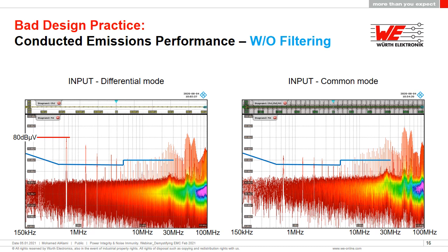Part of using an FFT as well, and using those power splitter and combiner boards, we were able to look at the noise content of the input signal. In this case, we're just looking at the input side of things, differential and common mode. So we've concentrated on the input side, naturally, and we've looked at the differential and the common mode content of that signal. So we've split that up using those splitters, and it shows us that there's quite a substantial amount of 630 kilohertz and its fundamentals of noise.